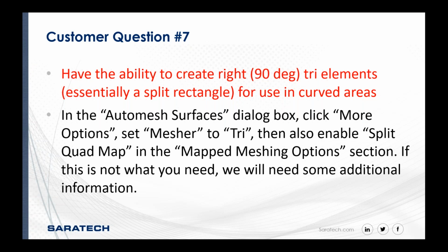Another thing that I don't have on here, but I wanted to mention, is what we call mesh approaches on surfaces. You can do a 4-corner mesh or a 3-corner mesh. You can essentially force FEMAP to use just 3 corners or 4 corners of a surface with any number of corners to get a better mapped mesh on that surface. I'm going to do a little demo later to show you some of the various meshing tools, so we'll get into that a little bit later.